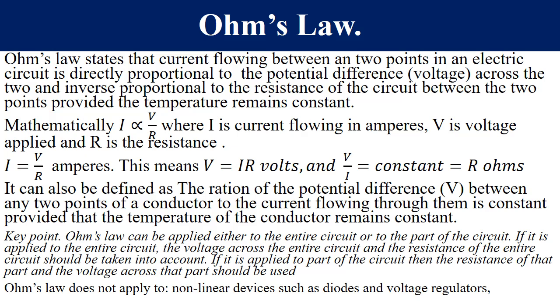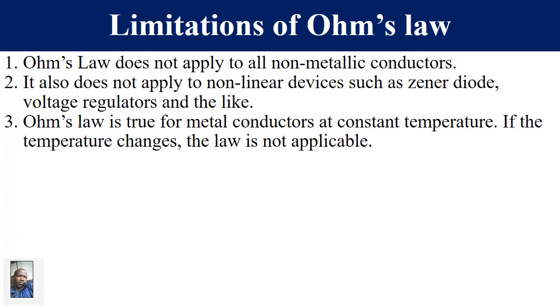Please take note. Ohm's law has some limitations, and these are, as I said in the previous slide, it does not apply to nonlinear devices such as Zener diodes and voltage regulators. Also, it does not apply to non-metallic conductors, and it is true only at constant temperature. And if temperature changes, it is no longer applicable.